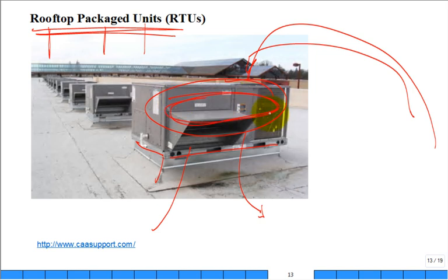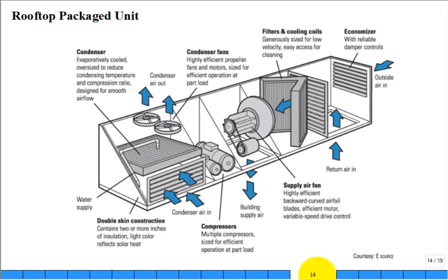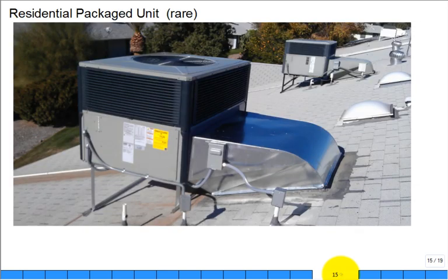The four major components are in that rooftop package unit, and they can have a whole pile of them on top of a Walmart or on top of a Costco store, or big box stores like that, department stores. You can look on the inside. You could find those components on those rooftop package units. They're going to have the evaporator somewhere, the condenser somewhere, the expansion valve, the compressor. Also, when the person is servicing them, they just have to get up on the roof. They don't have to get into the occupied retail space or anything, or shut anything down.